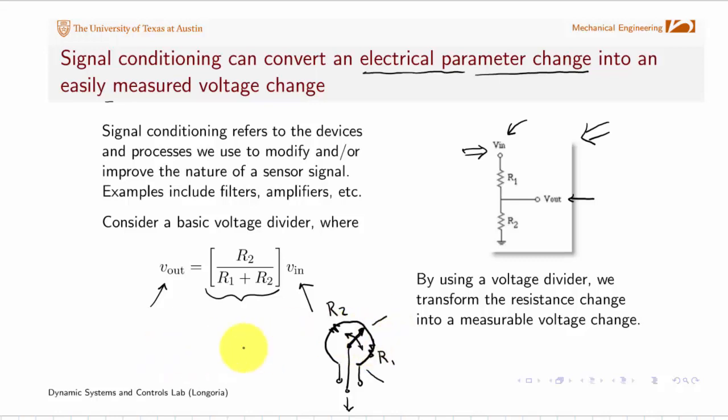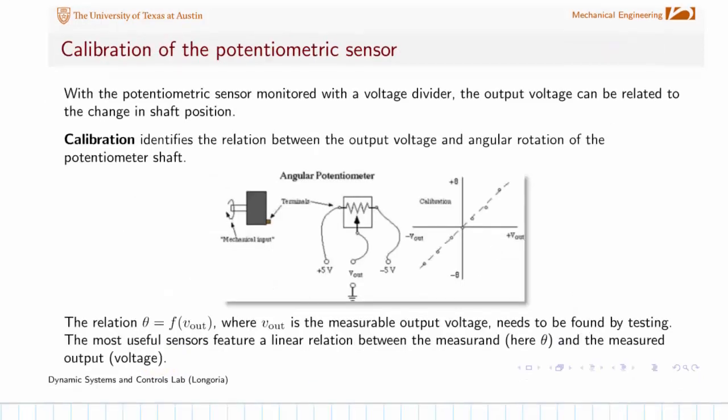They also make, by the way, linear potentiometers, so you don't have to have rotational potentiometers. There are a lot of potentiometers you'll see that are little boxes, and as this guy moves in and out, effectively in here you have just a linear potentiometer this way, and wherever this slider touches, you've got, again, two resistors in here, right? And again, you'd have the three terminals. So you can also find many linear potentiometers that are available for measuring linear, translational motion as well as rotational motion.